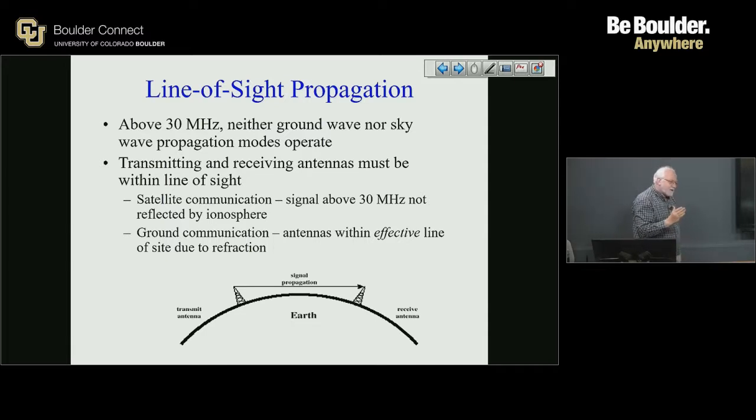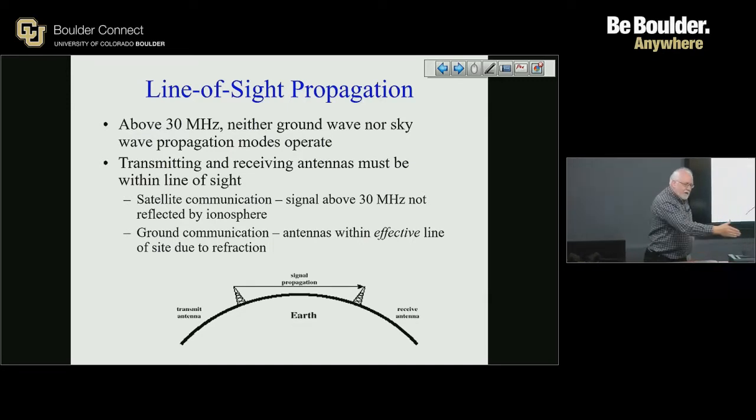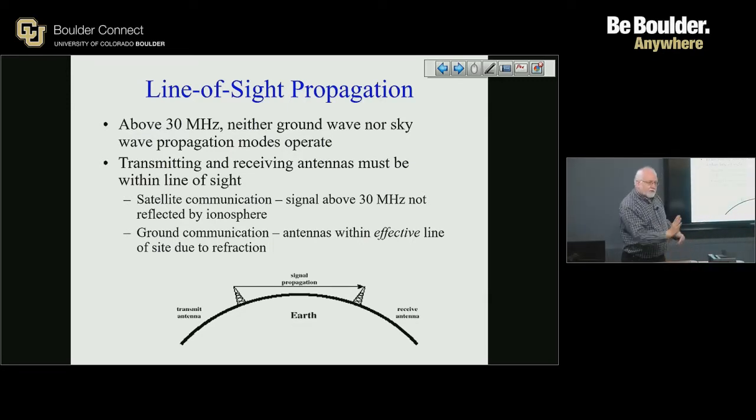And the reason for that is that when a vertically polarized signal bounces off a reflection, it changes its orientation. And it tends to help block, if you put the vertical antenna on the wall there, any bounces off the floor will come back to it at cross polarization, so you have a little bit less multipath. Whereas if you turned it horizontally, the measurements show that you end up with a little bit more multipath.